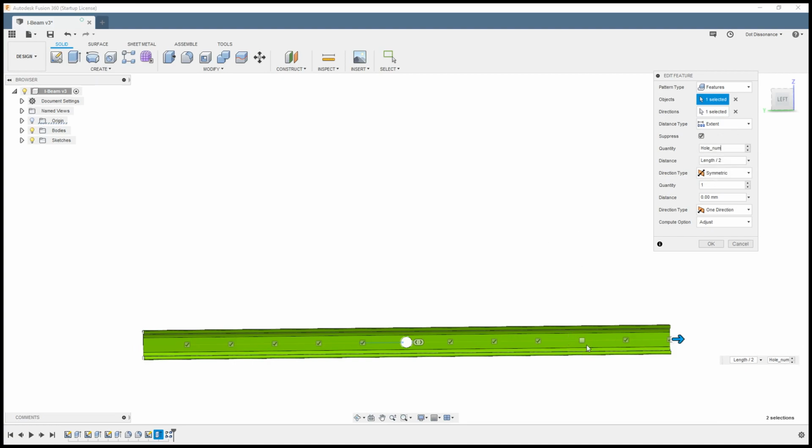But now look what happened. The numeric value that you chose of which one it was became unchecked. Now because Fusion's the way it is, there's probably somewhere in here that you could figure out which one that was and tell it to always be the one on the end. But I don't know. So we're going to check that one back, and we need to subtract this one. But if we subtract that one, it's going to keep changing. So we've got to adjust the original sketch. Okay, so I'm going to hit OK to this to leave it be for right now.